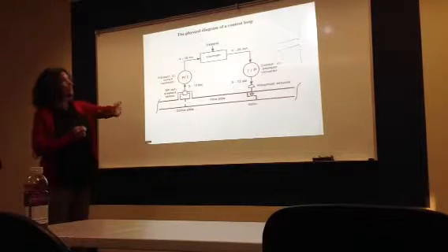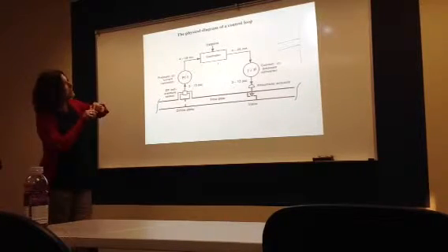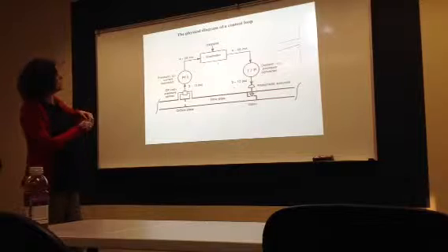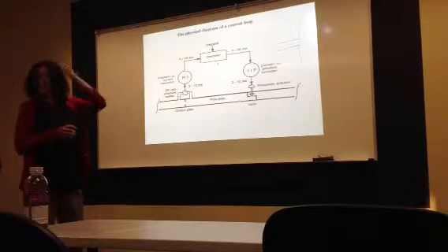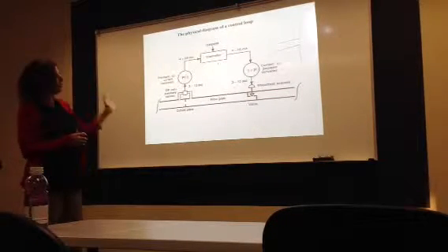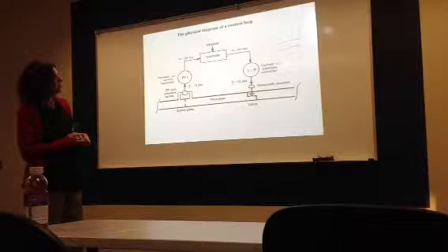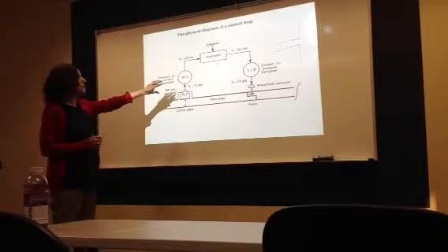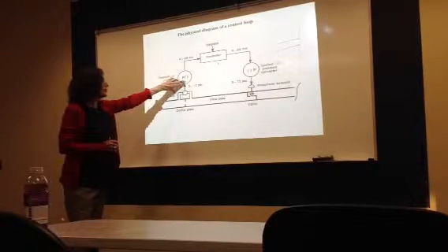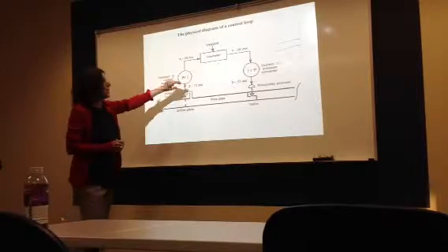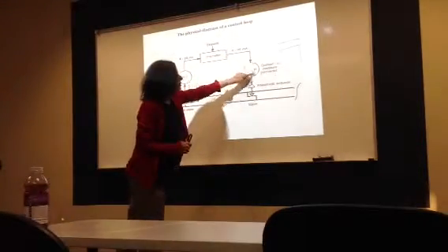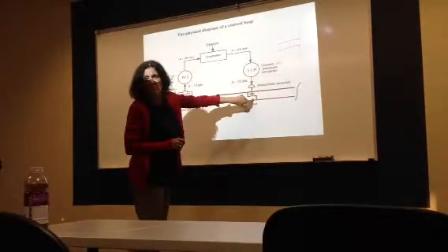what do we have? We have the physical diagram of the control loop. What are we trying to do if you look at that? Tell me quickly. What is the controller trying to do? Pressure converts to current. We have pressure to current transducer, and we have current to pressure transducer.